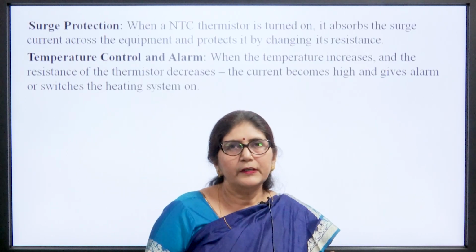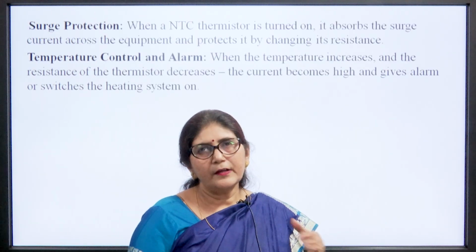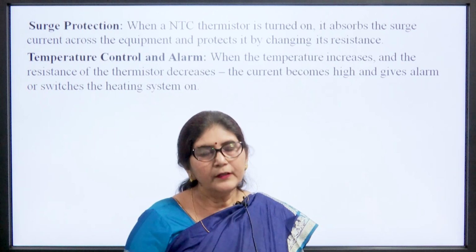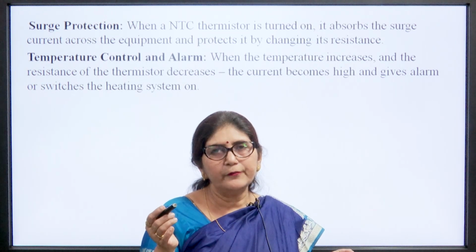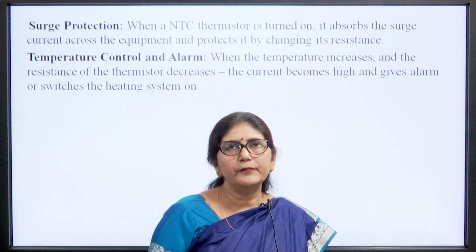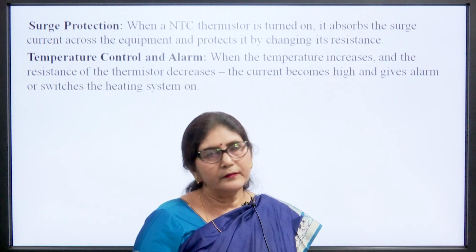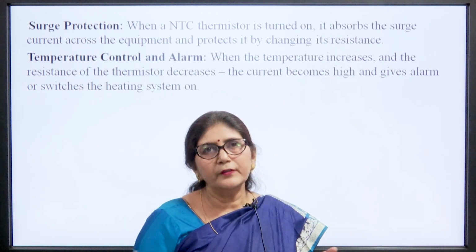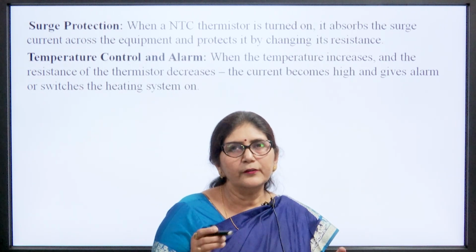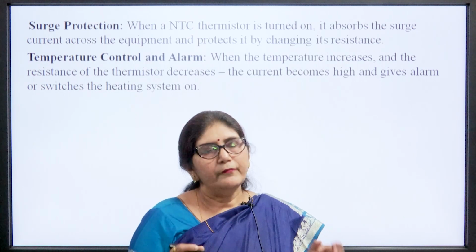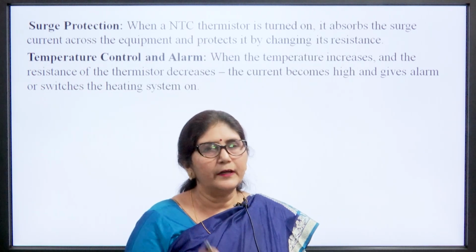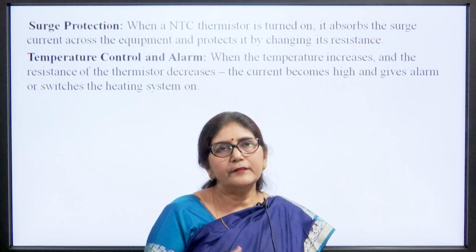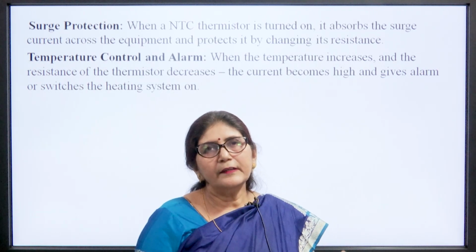Then it is used for surge protection. If a high current is flowing, we can use this thermistor, because after some period of time the resistance of this NTC thermistor will reduce. Similarly, for a temperature control alarm, when it has a high value of resistance, a small current is flowing, but in self-heating mode its resistance will decrease and the current will increase.